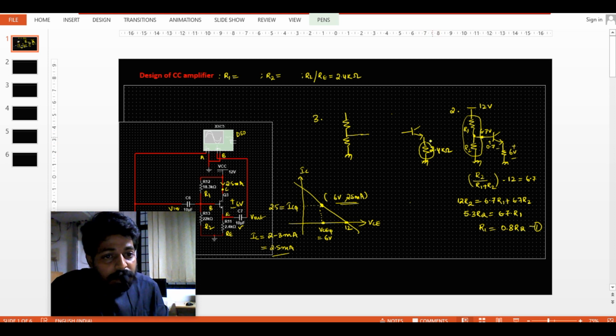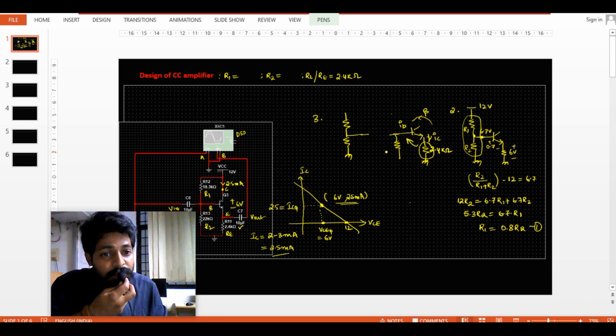If this resistance conducts the current IC, the branch where it conducts the IC, I will be moving into this branch where the current is IB. Whenever I move the resistance which is at the flow of current IC into the flow of current IB, which is exactly beta times or HFE times less, I have to scale my resistance that many times. So I can put my resistance over here, beta times 2.4 kilo ohms. Now I can erase this entire network.